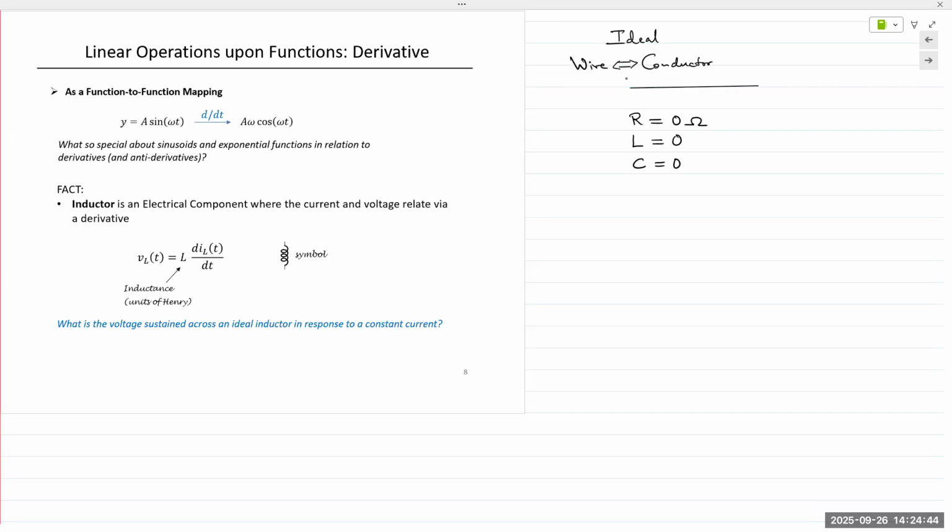Just going off on a little bit of a tangent. I think I spoke about a 100-foot long power extension cable, right? If you plug it into a power outlet, you would expect 120 volts to be available at the other end, 100 feet away. But in real life, that 100-foot cable would have some resistance, maybe 1 or 2 ohms, so it will affect the voltage. That 120 volts might drop to 119 volts, or 119.5, whatever. I'm just throwing out random numbers here.